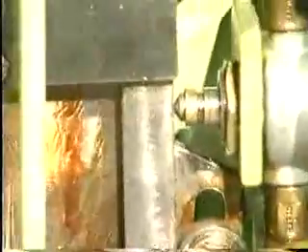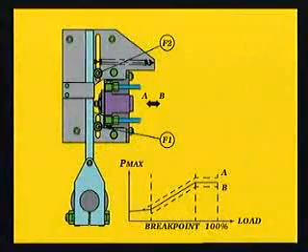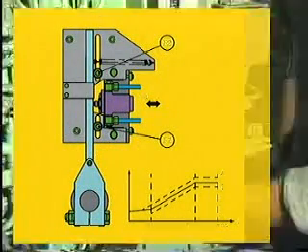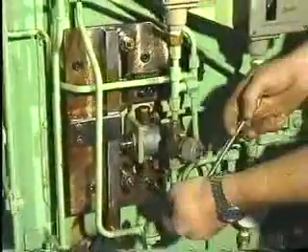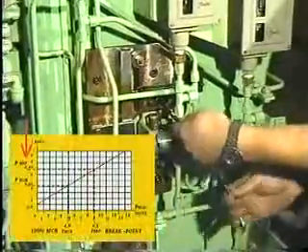Steel rod touches both pivoting points. Displace the pilot valve bracket until the calculated control air pressure at brake point is obtained.